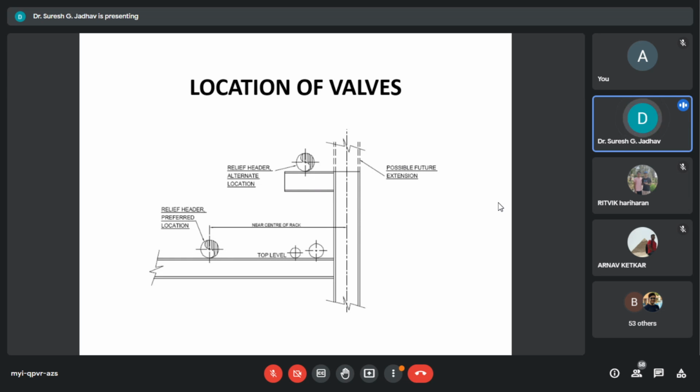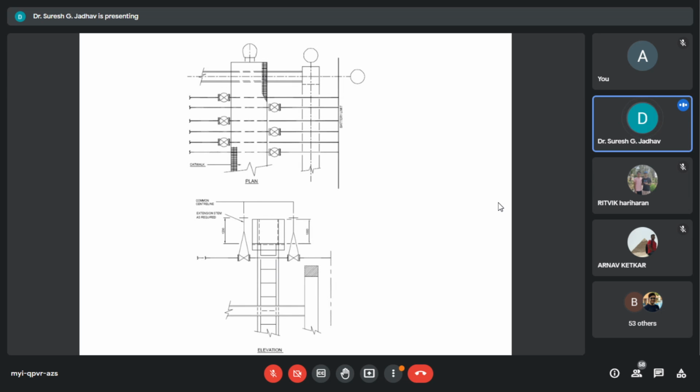In considering the regulation, that is 2.5 meter levels, control valves are usually located near the rack columns for convenient supports. Keeping the dimension between the B and C or D or E to the lowest required level will minimize the length of pipes between the rack and process. And we have to consider process parameters in this elevation, so we can change above or below the rack levels.